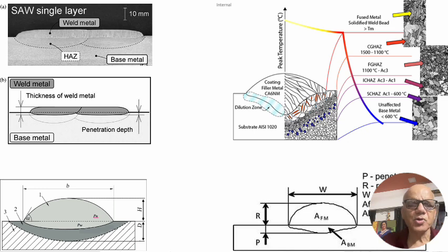So what are all the important parameters which we consider for butt welding also, but they become a little more important when we are going to do an overlay, where we are going to do a lot of layers side by side, and even a fine porosity, crack or inclusion in the surface of this weld will get attacked with the corrosive liquid.